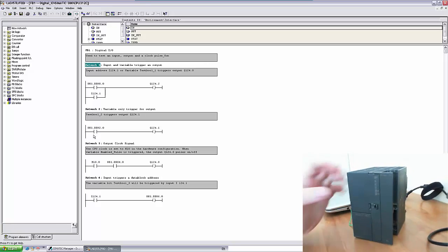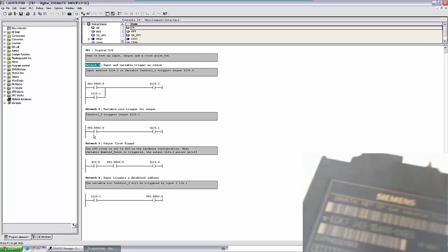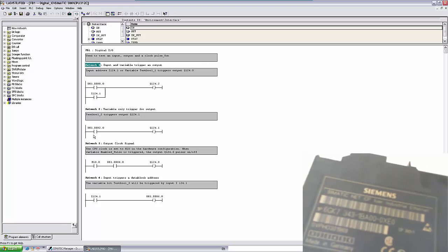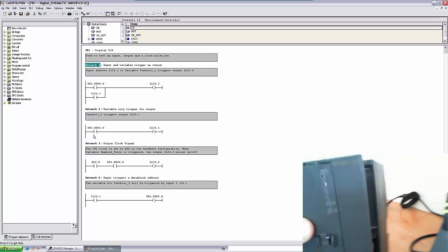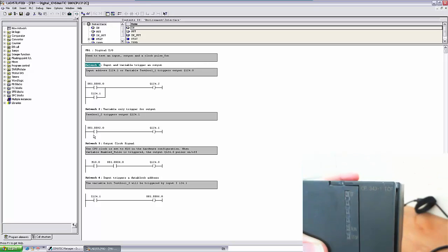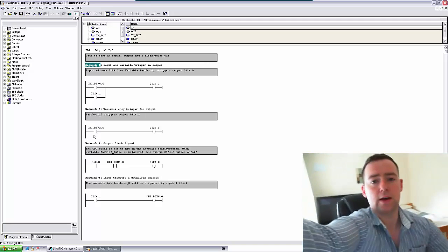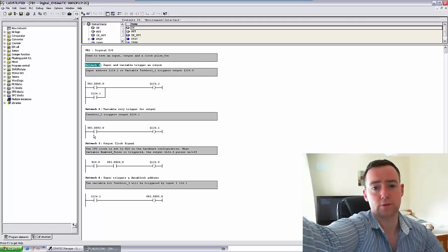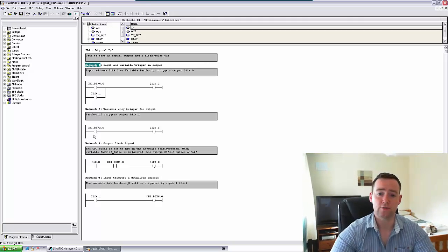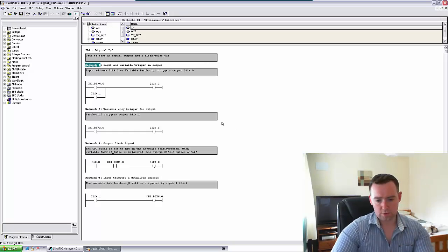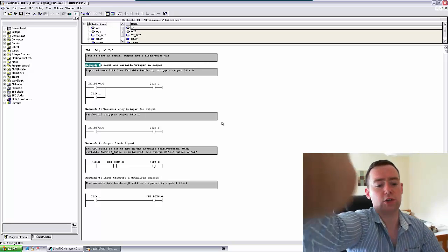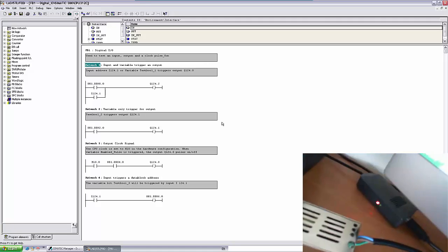Also, this is the most important thing, it's a Simatic NET CP for Industrial Ethernet, a CP343, and this is going to be used with the S7A driver as well, right? So what I'm going to do is use a PC-PG interface first, right, which is this one down here.